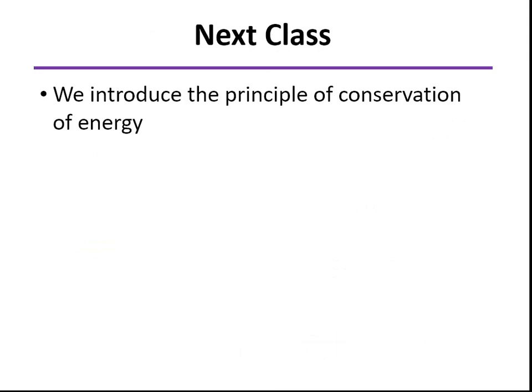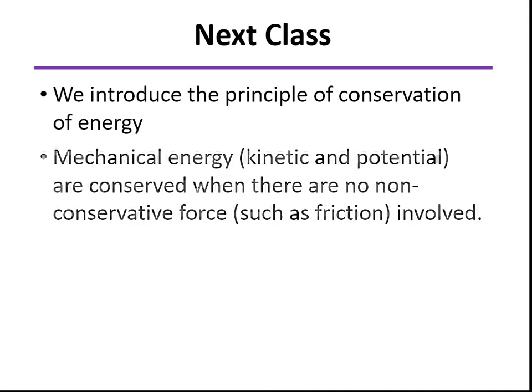So in the next class we're going to keep going with work and energy, but now we'll introduce the principle of conservation of energy. So when we talk about mechanical energy, we're talking kinetic and potential energy. And when we don't have forces such as friction, which we call non-conservative forces, in particular when we have weights and springs that are conservative forces, then we can look at work and energy in the form of saying that energy is conserved. So the total of kinetic and potential energy from one state to the other will be the same.